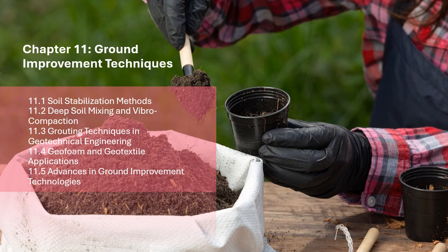2. Slope protection. Both geofoam and geotextiles are used in slope protection applications. Geofoam reduces the weight on the slope, while geotextiles provide reinforcement and filtration, ensuring that water is effectively drained away and preventing soil erosion. 3. Drainage systems.